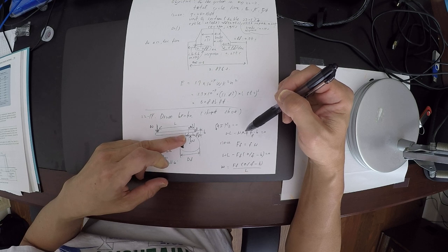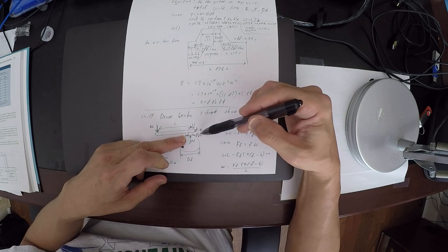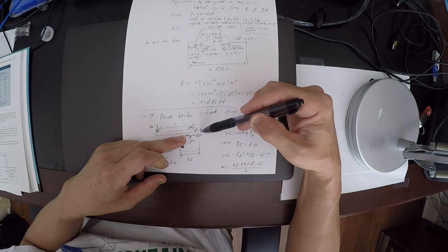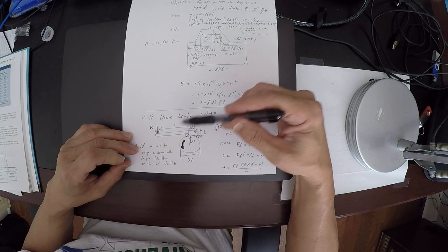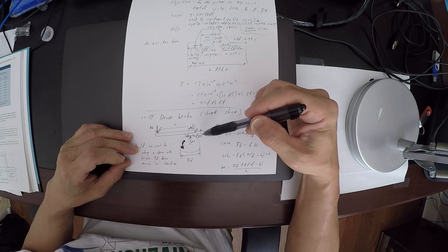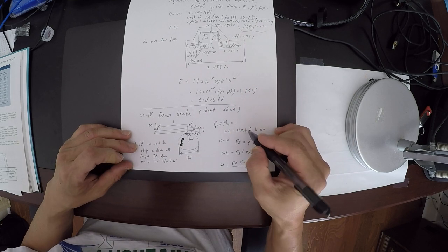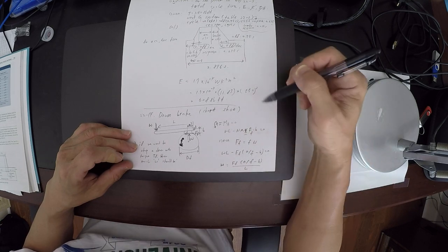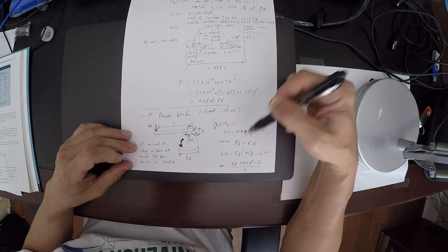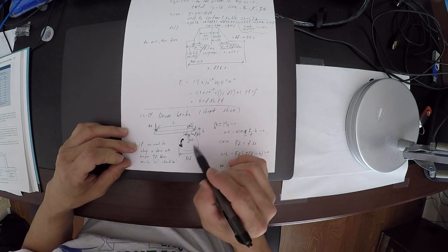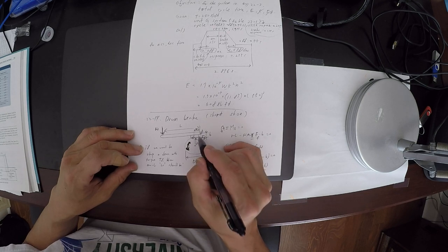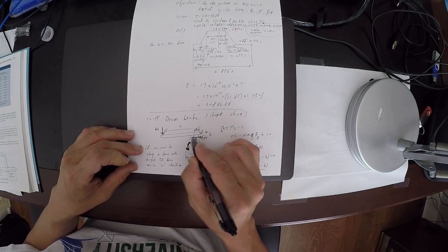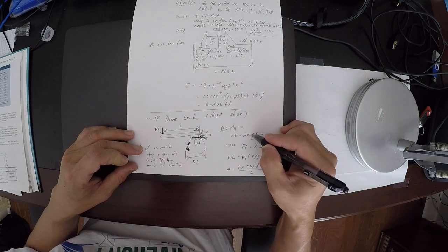And then another force that you need to consider is friction right here, because it is off from the center A by B. So Ff times B is going to cause, I think it should be negative. Sorry, negative moment. But this basically depends on the direction. If the drum was rotating this way, the Ff should be going that way. If it's going that way, this is positive, yes.